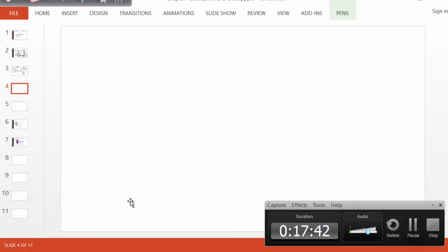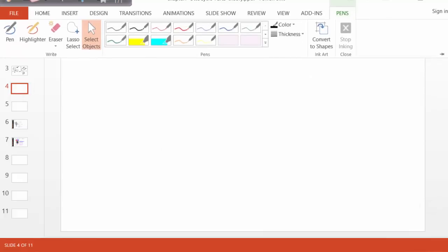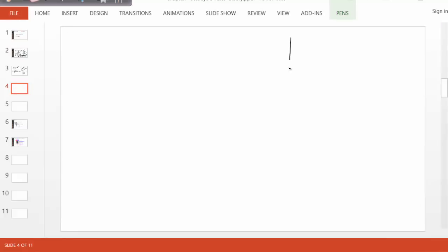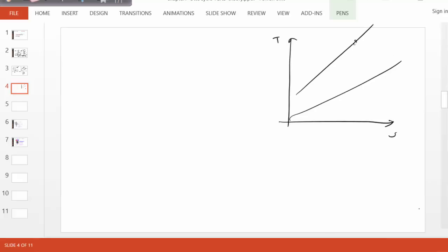Okay, let's do a new slide here for that. So to model the blowdown, this is 1, 2, 3, 4. From 4 to 1, heat is rejected, and we come back to state 1, and we assume volume remains constant and the system is still closed.